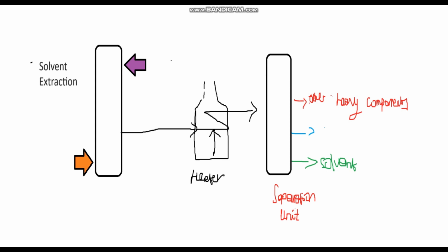Today, phenol, furfural, and cresylic acid are widely used as solvents. In the past, some refineries used the Edeleanu process, in which the solvent is liquid sulfur dioxide, whose hazards potentially made it undesirable. Fluorinated ethers and nitrobenzenes are others.